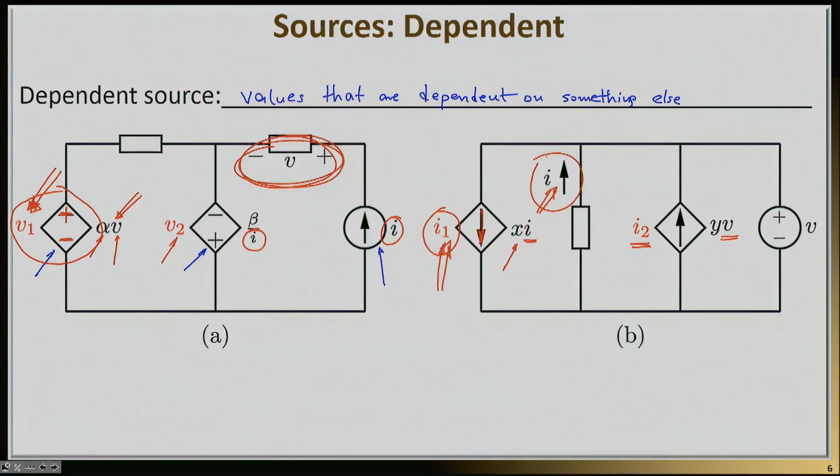And we give names to those things. For example, we call this very first source here voltage-controlled voltage source. So voltage-controlled, VC, signifies that this source is controlled by a voltage. Vs, the voltage source, signifies that this is providing a voltage to you. Or it could be this source here is a current-controlled current source, CCCS. And there are all different combinations. For example, this source here is a current-controlled voltage source, CCVS.